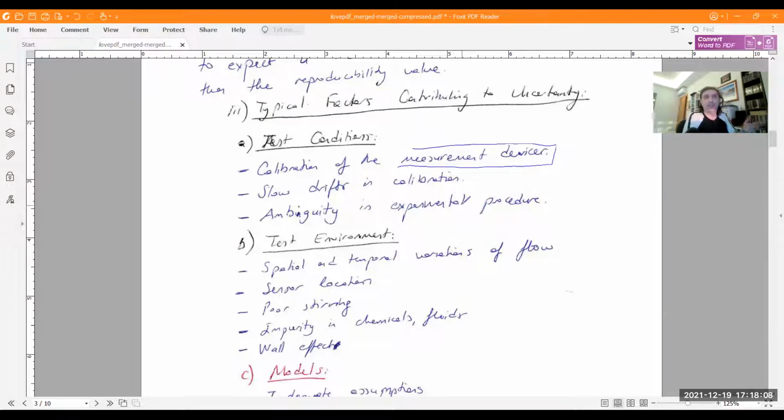Of course, you are not going to be conducting the calibration as far as I know, but from time to time, the measuring devices should be calibrated. You should know that. And this is very much related with the concept of slow drifts in calibration. Almost all sensors, all measuring equipment, and also generally sensors in chemical and process industries, lose their accuracy in time.